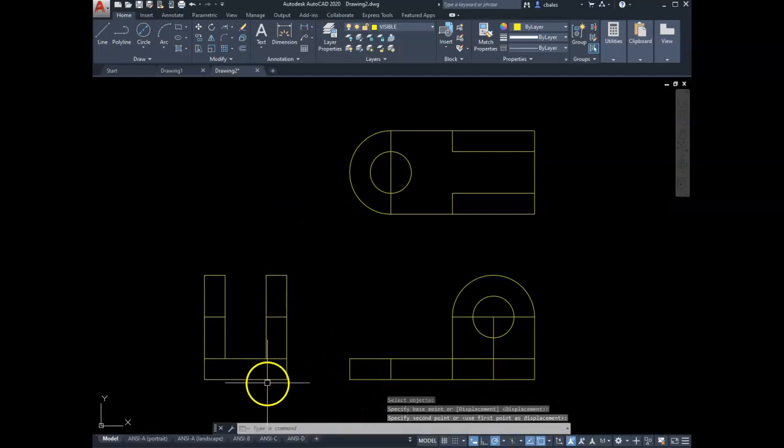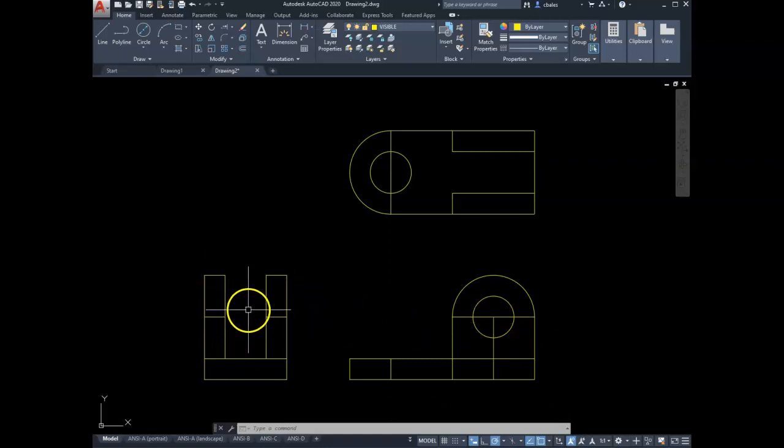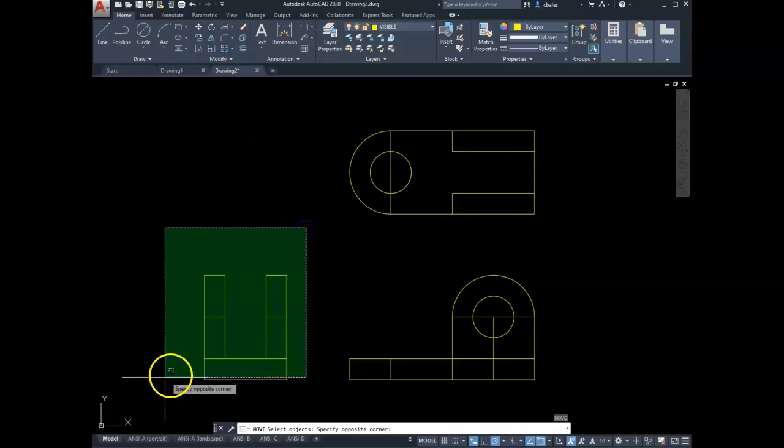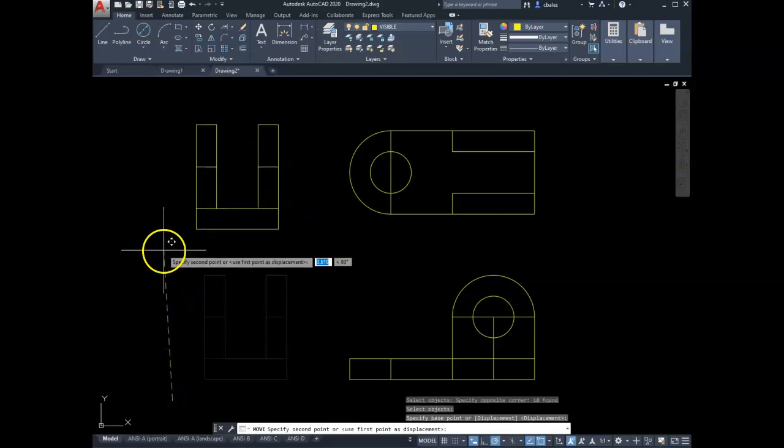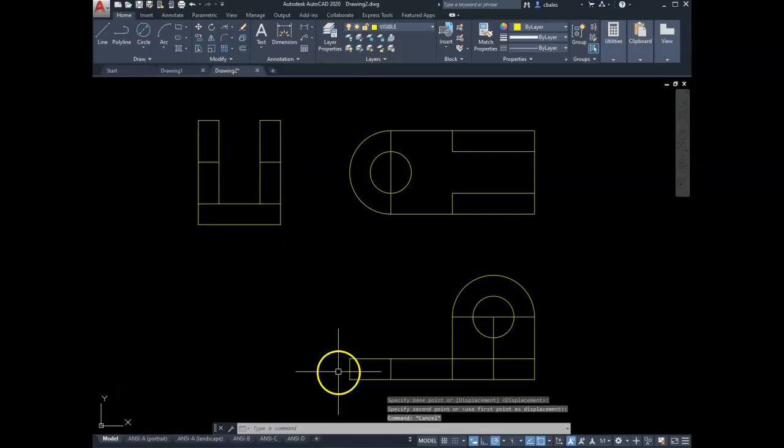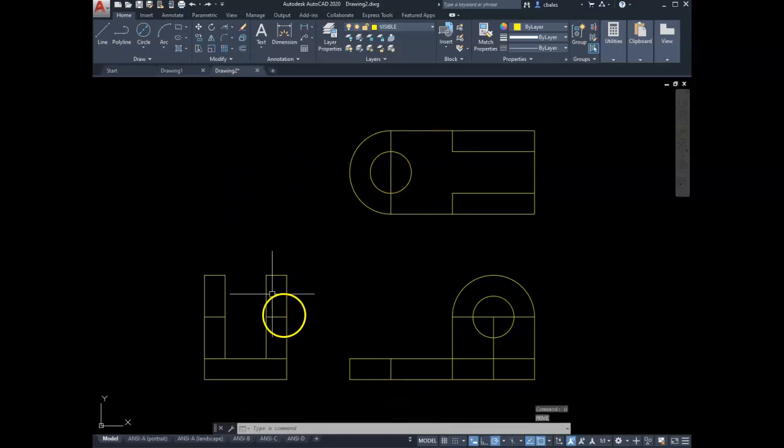So there's the left side view, and it's aligned properly in here. Now, you may be inclined to draw it here and then put it up here, rotate it. This is not correct. I hope everybody understands that that is not appropriate. That is not aligned orthographically with the top view. So how do we get this aligned? If we need to draw this here, how do we rotate this and put it up into the correct orientation? Well, that's the tricky part.